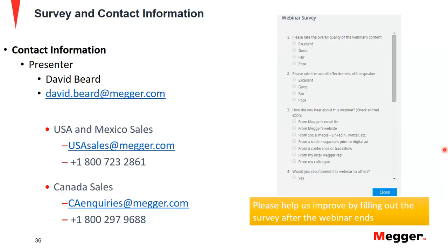Yes, we can absolutely test a breaker trip unit with the relay test set. We have a feature for recording time on our home screen, so anybody can use a pre-fault to fault home screen, provide nominal values on pre-fault, and then pick up values for the breaker trip on the fault state. All they need is a way to connect to the binary input of the test set.